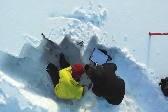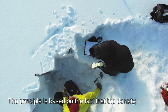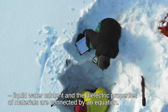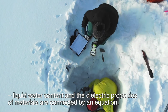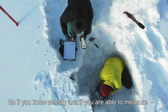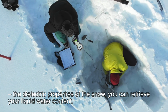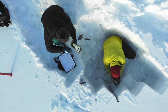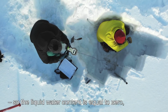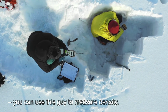The principle is based on the fact that density, liquid water content, and the dielectric constant or coefficient of materials are connected by an equation. So if you know density, and if you are able to measure the dielectric properties of the snow, you can retrieve your liquid water content. Or, for example, if you already know that your snow is dry, so the liquid water content is equal to 0, you can use this guy to measure directly the density.